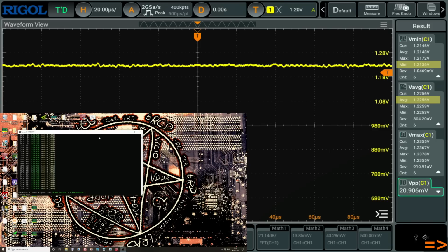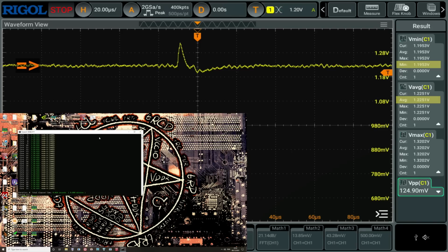And so every time the event timer does its thing, what's basically going on is we have Y-Cruncher running at a relatively constant amount of current draw because this is a 50 megabyte data set, so it fits almost entirely into the L3 cache of the CPU, and so there are no memory access related processing stalls, and so the current draw is relatively constant. But then Windows comes along, interrupts Y-Cruncher with the event timer, so we see the current draw basically reduce from the CPU side, which causes a voltage spike because there's a whole bunch of energy stored up in the output